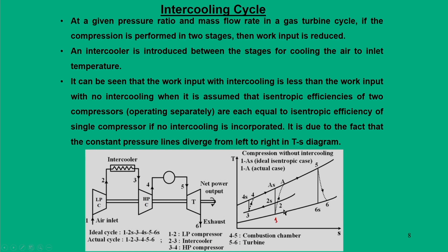Now, with intercooling, what does it do? After the first stage of compression, that means at 2 or 2s, the temperature is brought back to the original temperature, and then the second stage compression starts from that. So, this process now becomes 1, 2, 3, 4.